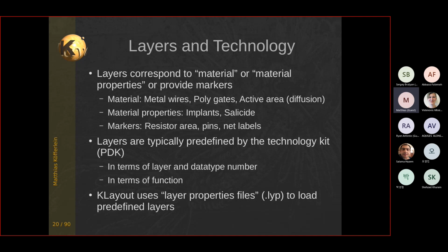When you open Cadence and you have a layer list, which in Cadence is on the left side, here it's on the right side, usually you have drawing layers, and drawing layers mean something. A drawing layer means, for example, a metal layer. So whenever you draw something, you expect that metal shape will happen to be where you have drawn it, like what we did exactly now. We have drawn a wire, we expect metal to be produced here.